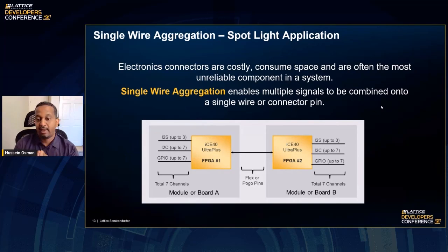And just highlighting the flexibility of an IO on an FPGA, an aggregation solution can take a number of interfaces through a single small FPGA, aggregate them over a fast serial interface, and then take them to another part of the system and break those out to the same interfaces. The key for using an FPGA here is latency and software support.